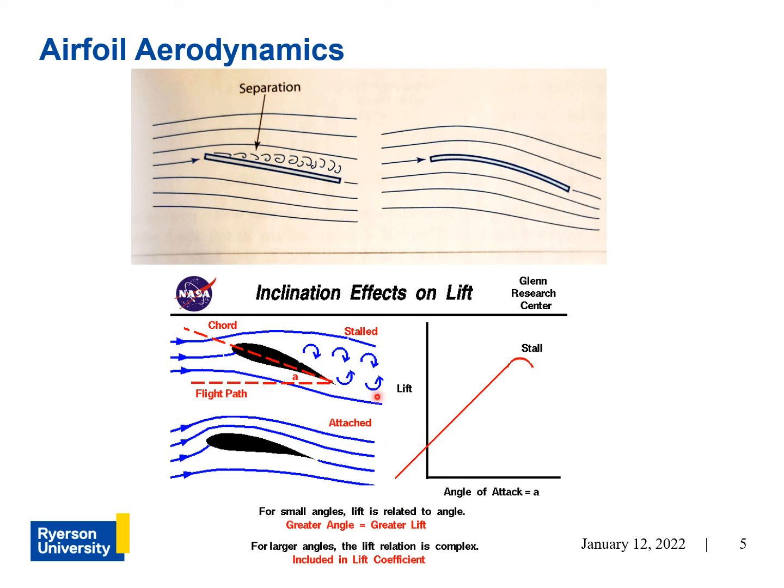And as you can see, the variation isn't always linear. As you increase your angle of attack, the flow will actually begin to separate, as you can see here in this diagram. And on the lift curves plot, it's represented by this region that's nonlinear, and it's called the stall region. And that represents the occurrence of flow separation because your angle of attack is too high.